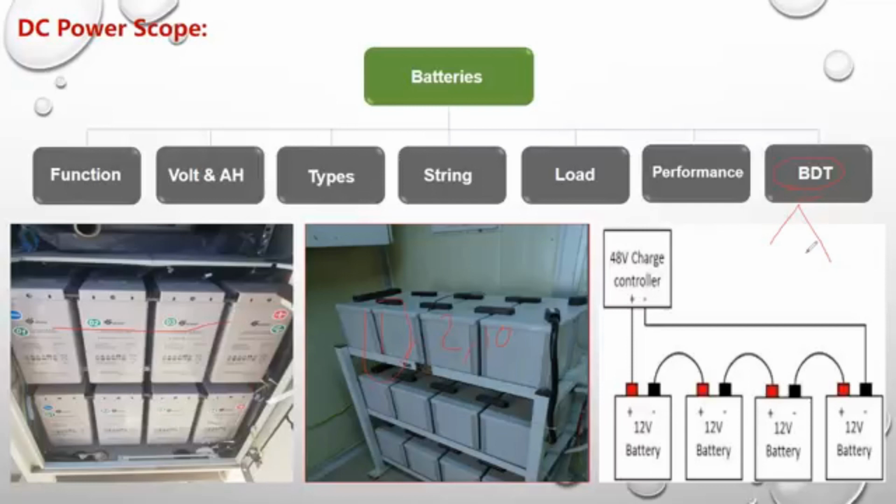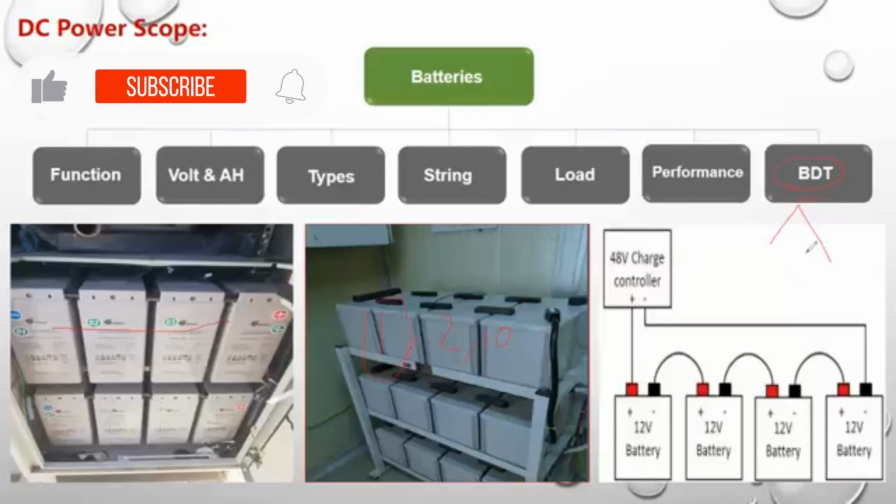Now, this battery discharge test is done by forcing the battery to discharge, by cutting off the electrical current source that is coming to the site. So I cut off the breaker cable that supplies the electricity to the rectifier. So the backup batteries start to work. And after the backup batteries work, I start measuring the volts of the batteries compared to time.